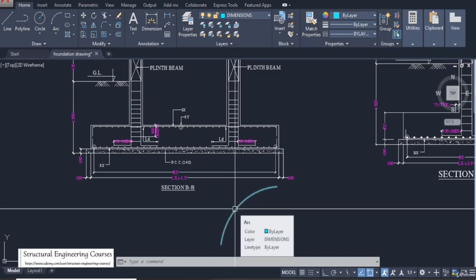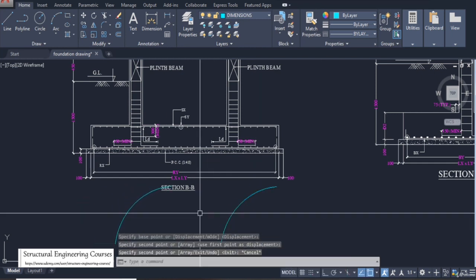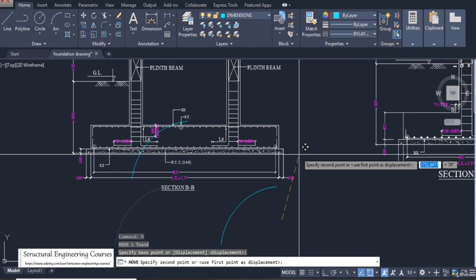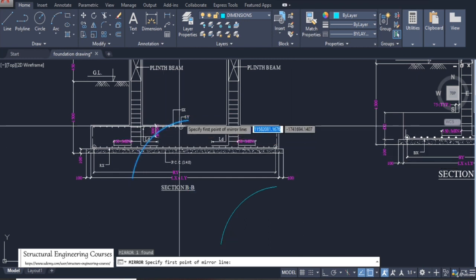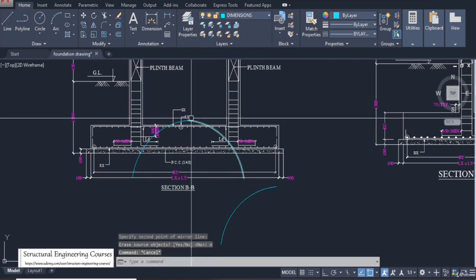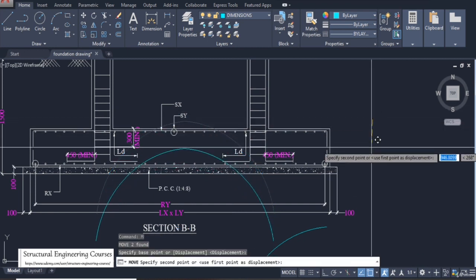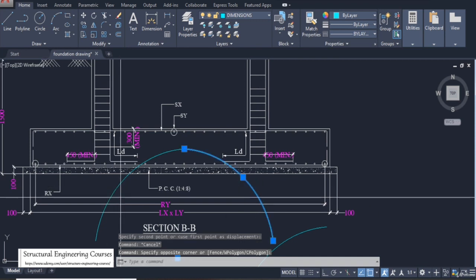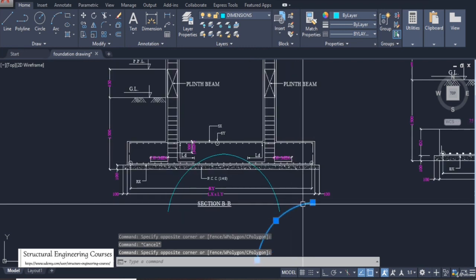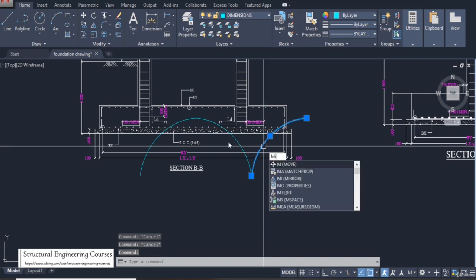So if we want to draw the profile of that particular bending moment, in some cases it might happen that it goes on the top, whereas in some cases it might not go on the top and it might be on the bottommost point only. So that also we do need to check in the case of the combined foundations. All these things are the basics without which you may not be a good structural designer.